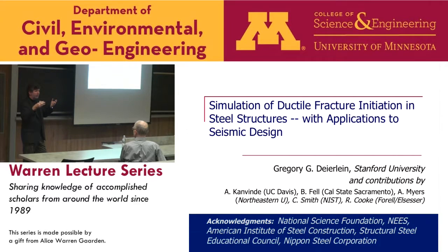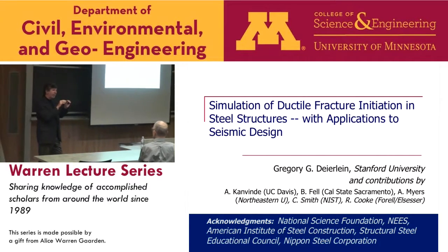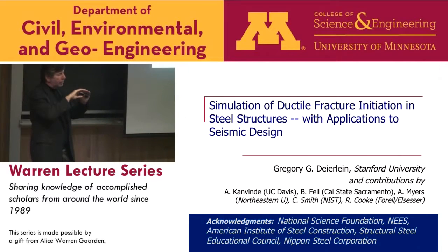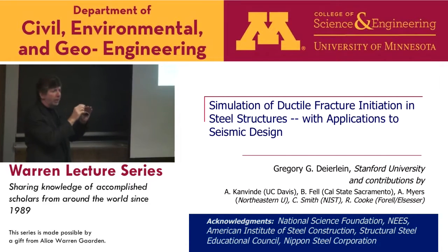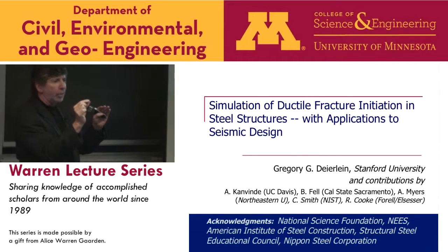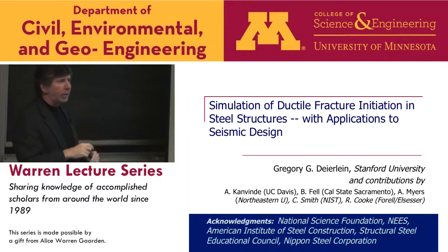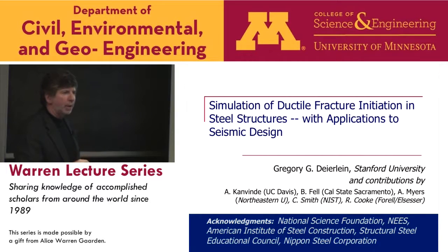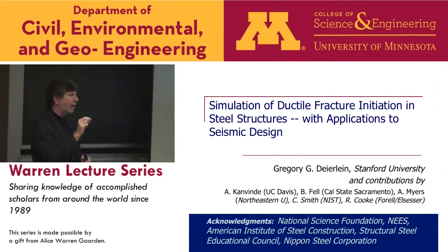We take one mesh and typically, if you don't have a sharp crack existing, the stress and strain gradients are gentle enough that even though they look sharp macroscopically, when compared to the critical length of 0.2 millimeters, they're pretty gradual. So we felt we could sample. We didn't have really a sampling problem, we think. Our element size might be on the order of 0.2 millimeters and we sample at that level. So the randomness was really just all in what we considered to be the capacity of the material.